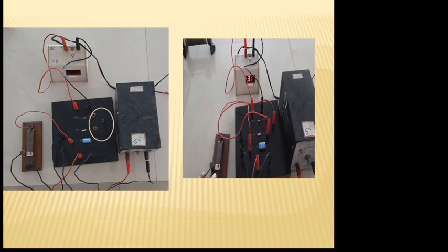Positive terminal is going here to positive, negative of the power supply is going to negative. The three-way key we were talking about, this black button, the pressing button, will go to the lower terminal. It is quite easy because L, M and U are written here, and here also L, M and U are written, so you have to connect accordingly. So it's not at all an issue how to connect it. DVM is written, so there we will be connecting the digital meter, correct?